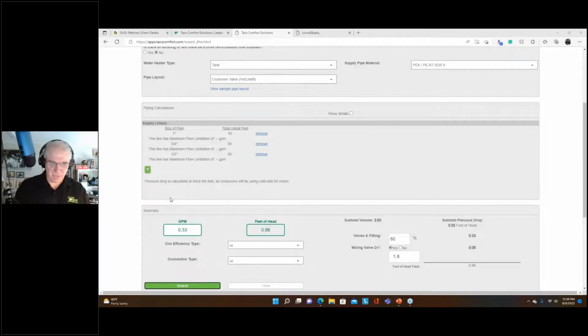So it's a question. Does the homeowner expect to have hot water at every tap instantaneously, 24/7, day or night? Don't give me any excuses. Pulse mode it is, right? Or do we have a situation now with people working at home? Is hot water usage all over the place? I mean, we don't have a set time when we take a shower or do this other stuff. Then maybe pulse mode would be a good idea then.